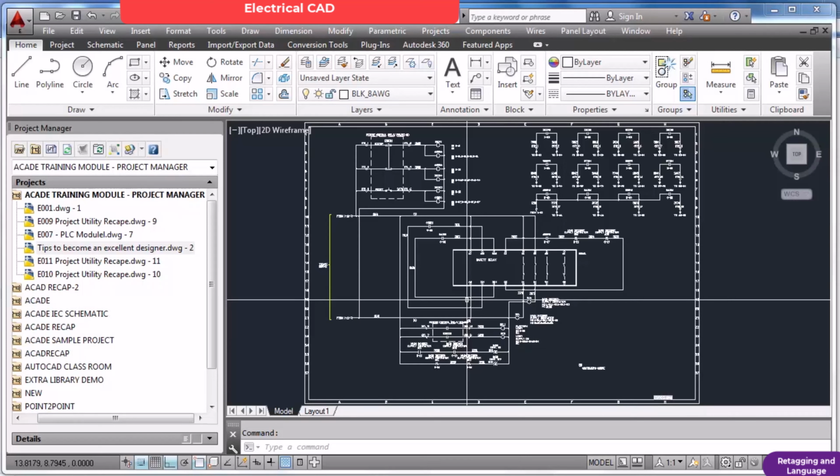Normally what I do is, if we can accommodate one set of drawings in 2 or 3 sheets, I will provide 5 sheets, because in future we may require to add few more drawings. So I will provide 5 sheets for a particular section, next 5 for the next section. In that way we should plan initially before start doing anything.